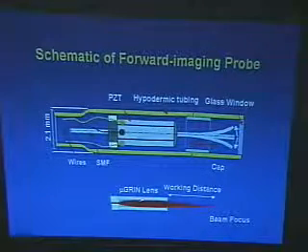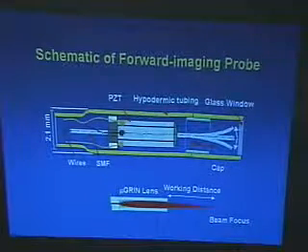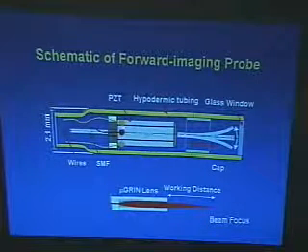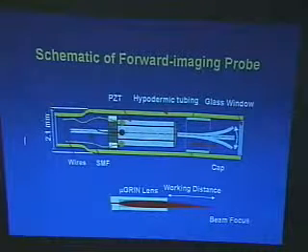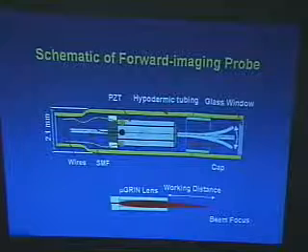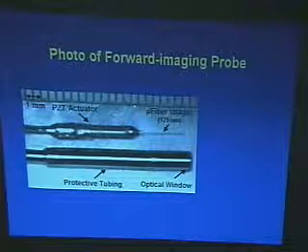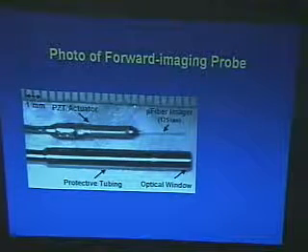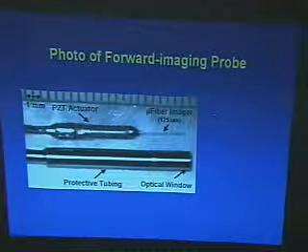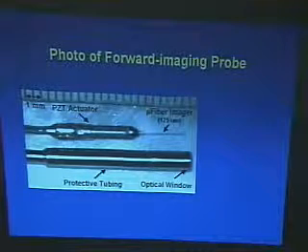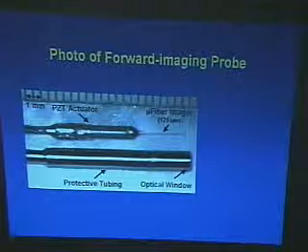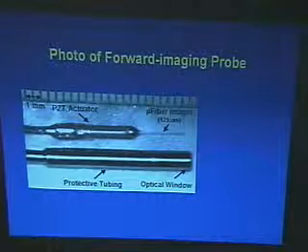So the entire imaging probe is about 120 micron. But the big footprint is limited by this piezo actuator. But again, we are able to achieve 2.1 millimeter overall diameter. Here, just to show some examples, Dr. Liu, a postdoc in my lab, developed recently this PZT actuated small imaging fiber. We can do forward imaging. We can scan in the X direction or the Y direction or at the same time. So you can do line scan or you can do 2D scanning.